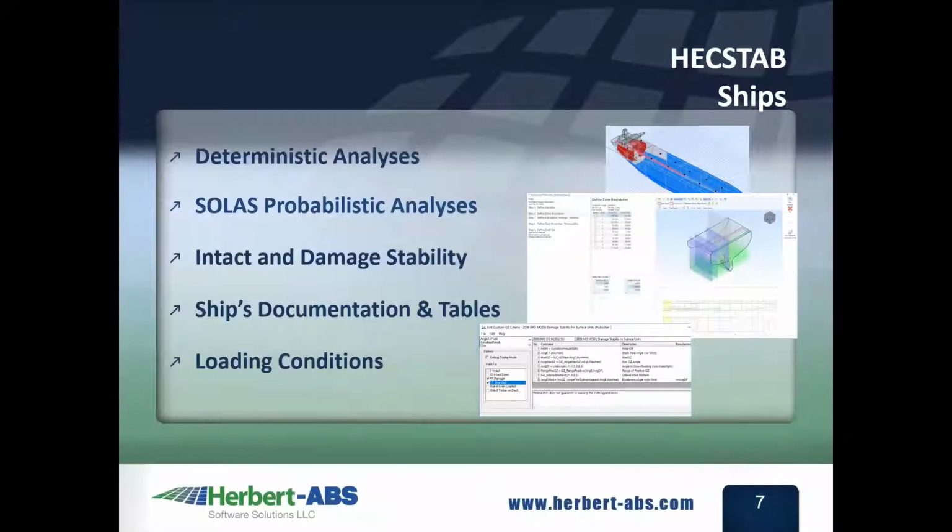We can do more advanced probabilistic analyses like those defined by SOLAS, looking at a wide range of possible damage cases and making sure that the overall survivability of a design is being met. Basic intact and damage stability calculations, as well as doing things like the standard ship documentation and tables.